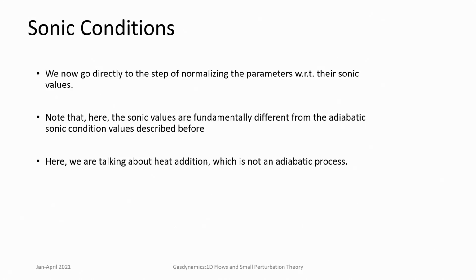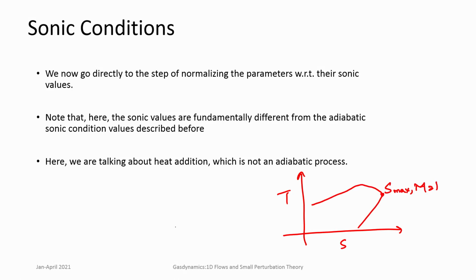You look for a reference condition, and for a Rayleigh flow there exists such a reference condition, the maximum entropy point S max, which corresponds to Mach number equal to 1.